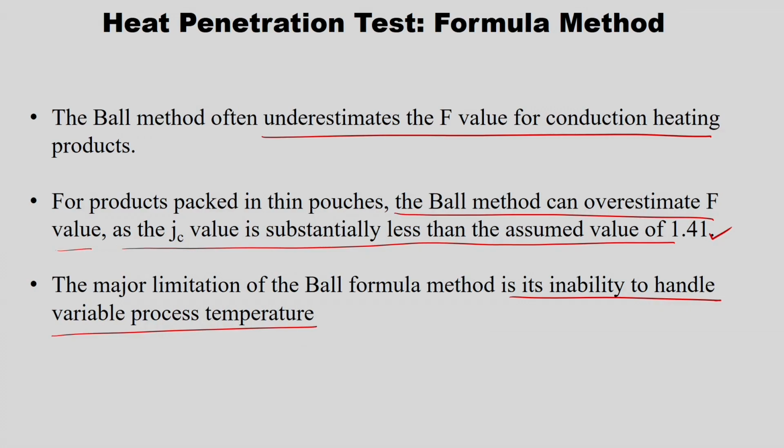Apart from that, there are numerical methods. It uses the finite difference method to calculate the heat penetration curve. It does two things: analyze and calculate. Analyze, in the sense that using the FDM approach, it calculates the heat penetration test, gets the parameters from there, and calculates the F value for process establishment. There are other numerical packages as well. I would like to request you to check a few reference books given in this lecture, so you will get to know the other methods.